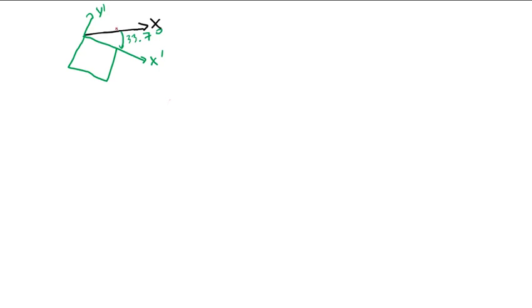Now, the stresses on here are going to be, each of these is going to be 200 psi, all in compression. At the point of maximum shear stress, the sigma x and sigma y are both equal, and they're equal to the average, which is the negative 200 we got before.